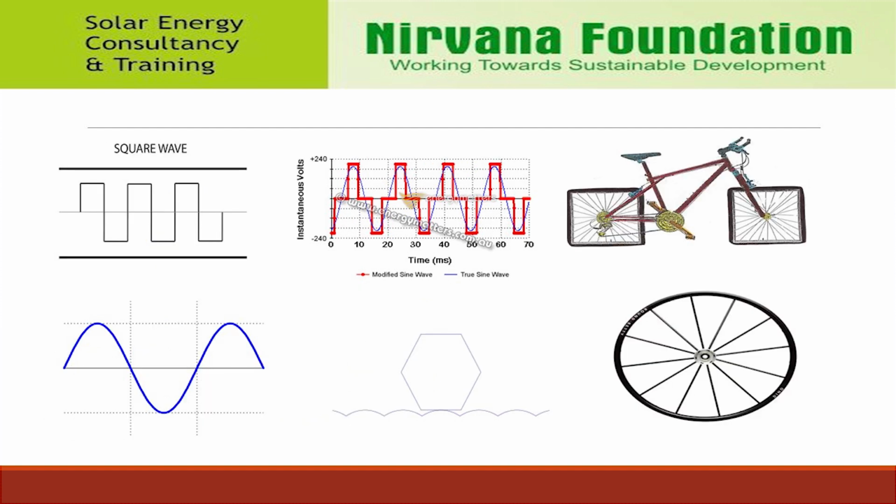Square wave. The square wave is more complex than a sine wave as it contains additional odd harmonic content. When viewed on a waveform graph, it can be seen that the amplitude instantly changes from its minimum to maximum value. There is no smooth transition as seen in the sine wave. The power of each harmonic in the triangle wave is twice as low as their counterparts in the square wave. Thus, the power of the harmonics in the triangle wave is reduced twice as fast as in the square wave.